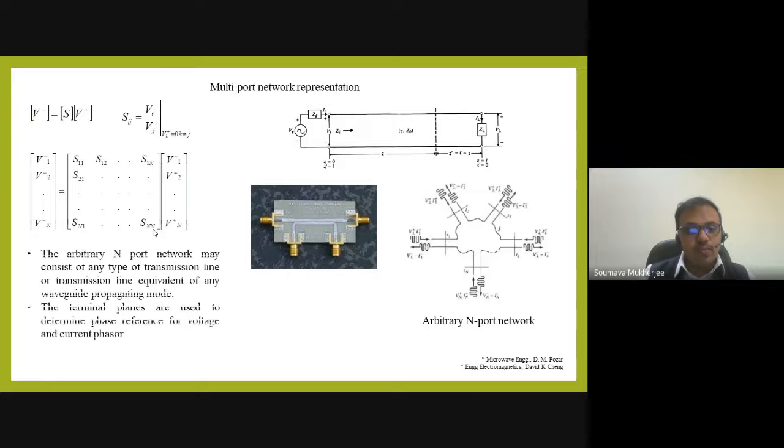Now, in a similar way, we can follow the logic for this kind of scenario. For a microwave circuit, we actually try to measure this S matrix rather than the Z or Y matrix. And from the microwave circuit concept, we can show that once we get this S matrix, we can convert it into a Z matrix or Y matrix. There are formulas for that. So the step is a little bit elongated from the conventional circuit theory concept.